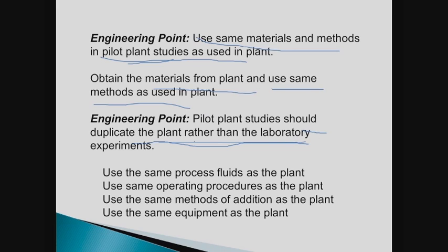I said this pilot plant-wise, but also laboratory-wise. Both the pilot plant and the laboratory should try to duplicate what happens in the plant, at least to some degree. Same fluids, same operating procedures, same method of addition, same equipment, perhaps. Now, that may be difficult to do, but it may save you a lot of grief.